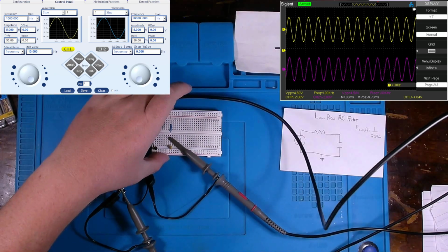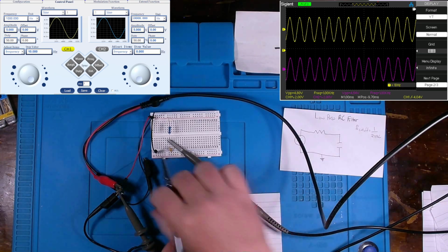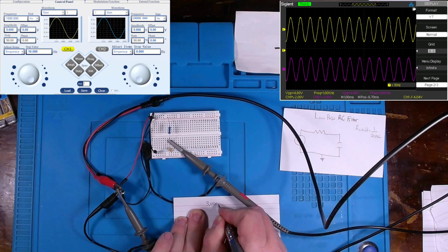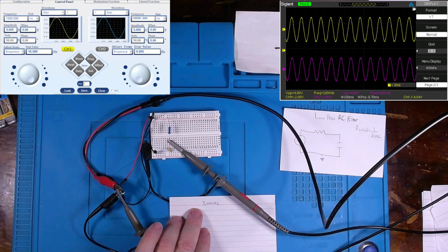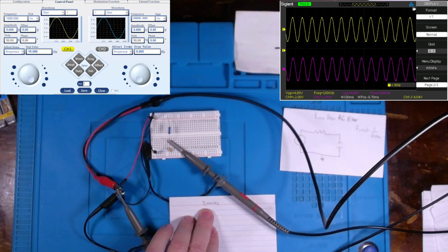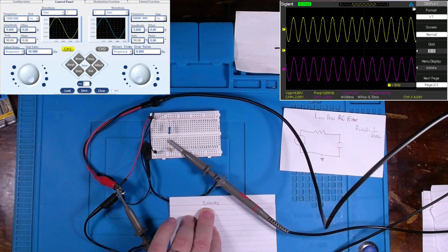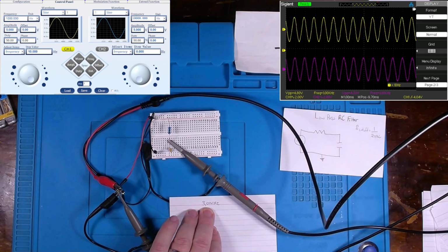And I'll move this up. I wanted to establish a cutoff frequency of something around 3,000 hertz. Okay. Typical audio transmission, some audio source is modulated onto an AM carrier frequency, amplitude modulated onto a carrier frequency.